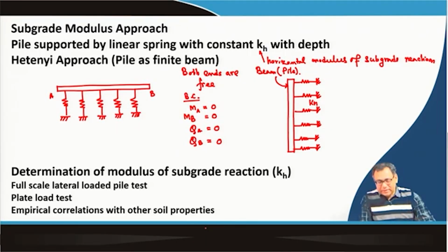As these boundary conditions have to be satisfied for the finite beam, we apply some end conditioning forces, M0 and P0 at A or M0 and P0 at B, so that the net bending moment and shear force will be zero at end A and end B.